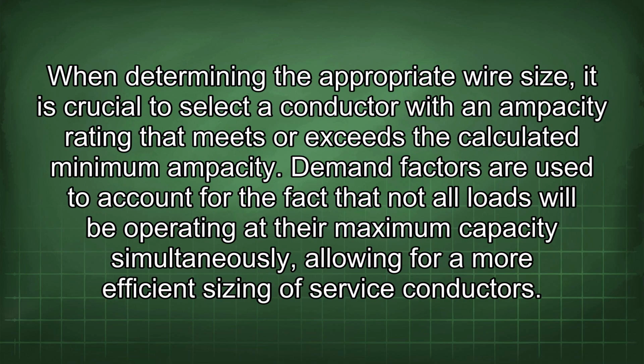When determining the appropriate wire size, it is crucial to select a conductor with an ampacity rating that meets or exceeds the calculated minimum ampacity. Demand factors are used to account for the fact that not all loads will be operating at their maximum capacity simultaneously, allowing for a more efficient sizing of service conductors.